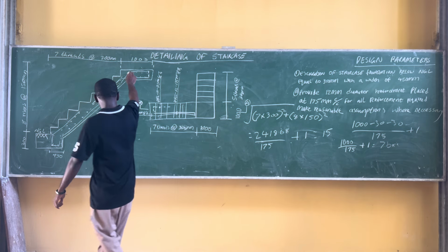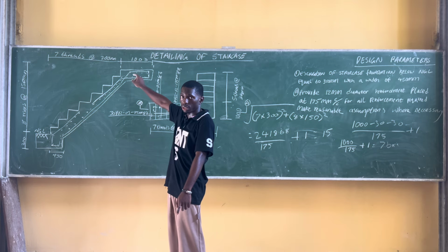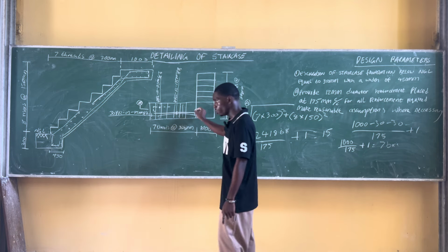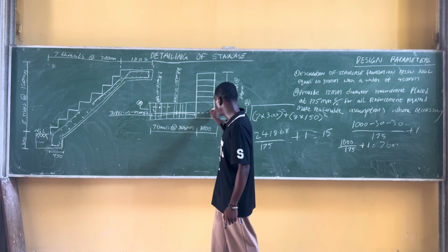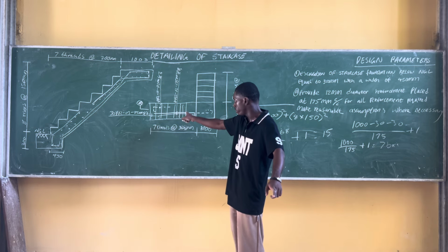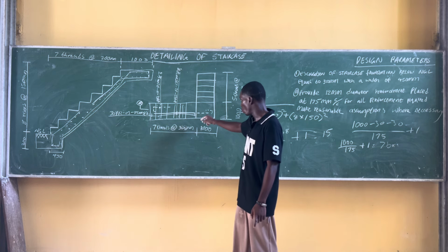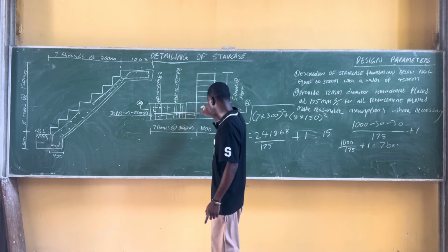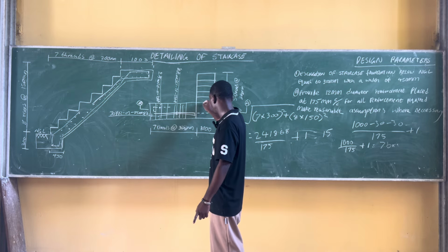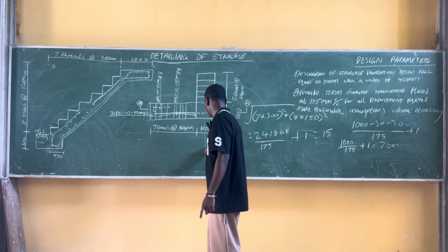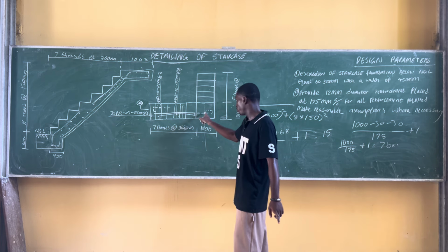And this, our B1, turned to a top reinforcement when moving towards this slab, which is 1000. So when drawing the sectional view, it will be like this: dash, dash, dash, dash, then a hook, dash, dash, dash, because it's indicating that this turned to a top reinforcement. So when I want to draw it like that, I'll just do a span. This reinforcement is moving from here to here, which is 1000. So I'll just draw out my colored line, put a reinforcement, indicating this reinforcement here.